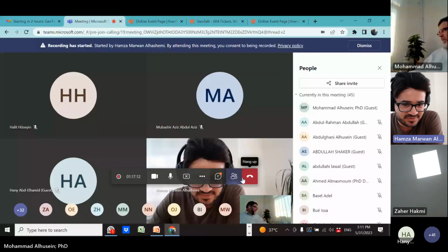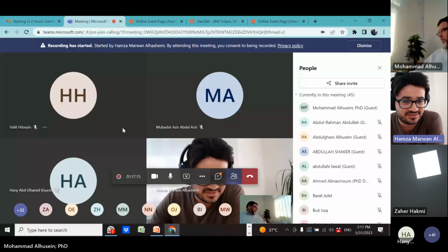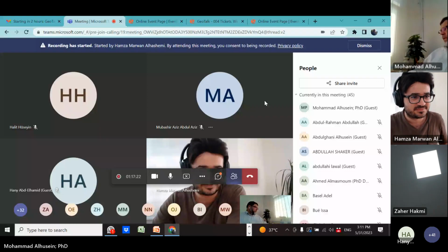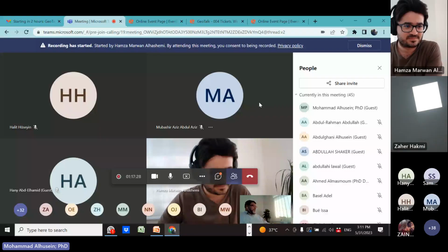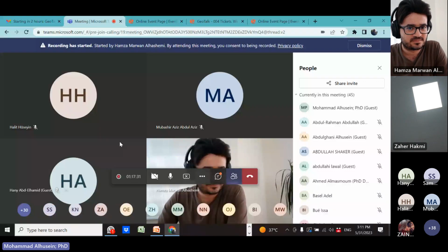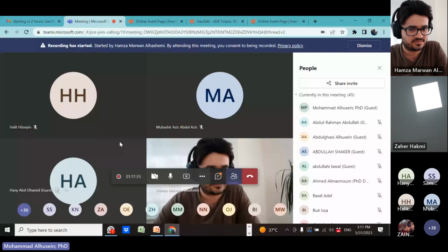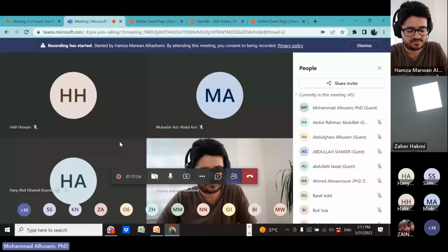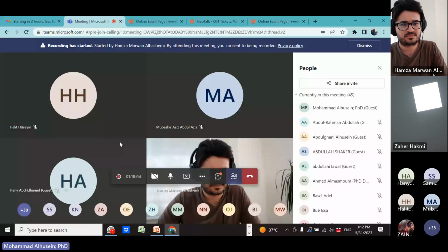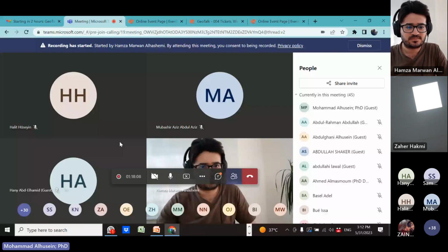He said, what is the typical laboratory test to identify high presence of calcium carbonate, and how to identify the high cementation? First of all, he has to assign not an expert geologist, but a geologist with a certain understanding of soil sample description during the drilling and also in the labs once they receive the samples. How to describe and identify the nature of the material, and then take the samples and prescribe the type of tests to be done on this kind of material.